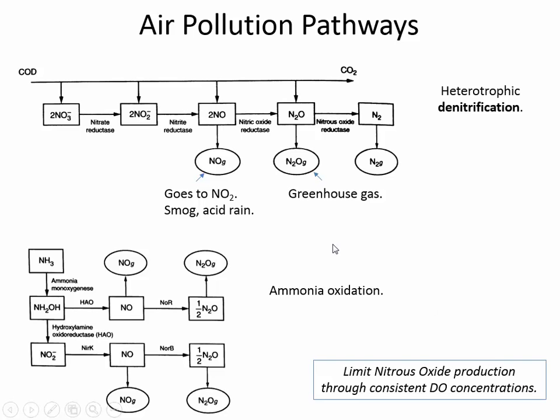It's when the dissolved oxygen concentrations fluctuate a lot that there seems to be the most emission of air pollutants. And so a reactor that is not in steady state is going to emit more air pollutants than a reactor that they can keep steady, where the bacteria aren't stressed and there isn't an accumulation of any one of the chemical constituents along the way.